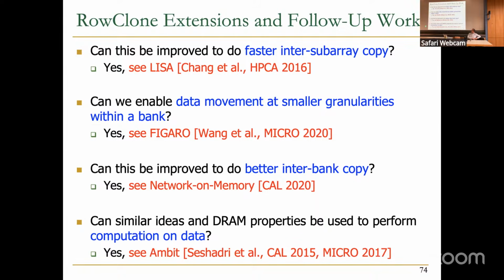And also your processor needs to be able to ship the operations to the memory controller so that the memory controller can execute them. That's going to be true for essentially everything that we're going to discuss going forward, because you need to be able to specify these operations, the processor should be able to ship them, and the operating system should be able to allocate the pages that you operate on in the right places in memory. So processing in memory requires changes across the stack, but some of the changes may need to be small, depending on whether or not those operations are already expressed in the ISA. So it's good to think about that.